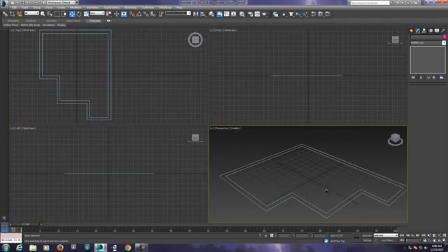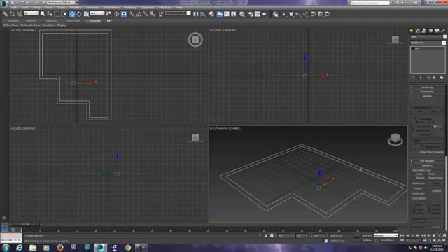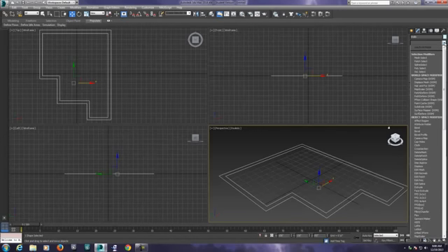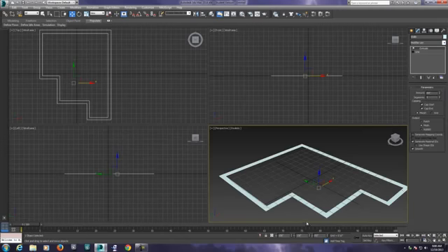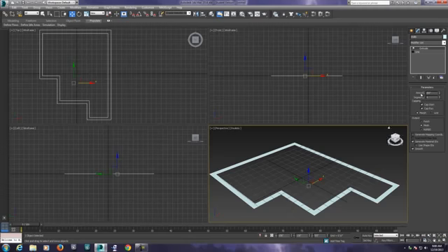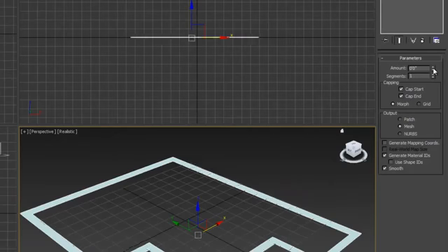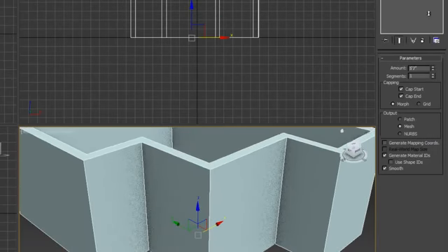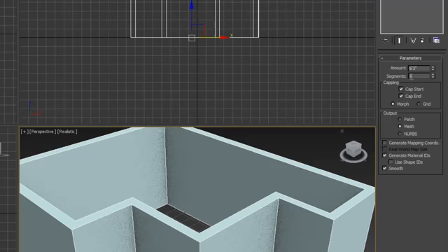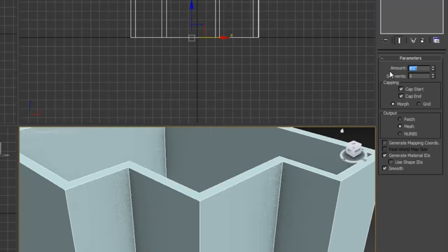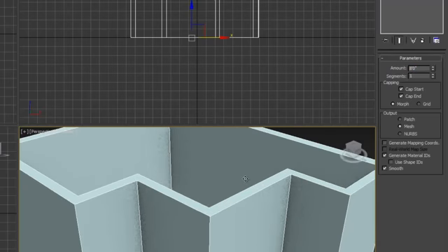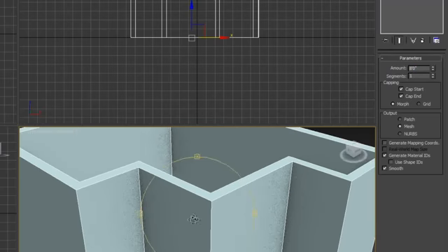Now we're still working with a shape here. And the next part I want to do is extrude. So I'm going to go out to my modify panel and find my extrude command. What extrude is going to do is give me a thickness of the walls in between the 2 splines. Now, if you look over to the right, we're still in architectural units, so our amount is going to be approximately 9 feet. You could actually key in 96 inches, and that's going to give you 8 feet, which is, you know, 8 or 9 feet is about right. I'm going to say 8 for this tutorial.